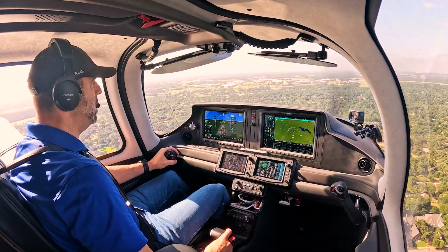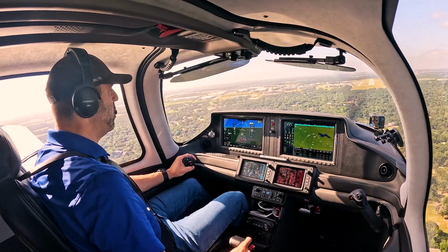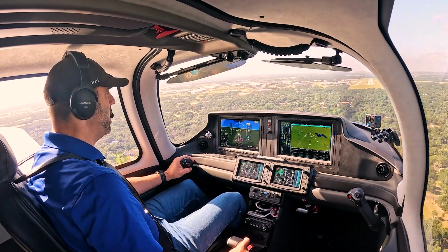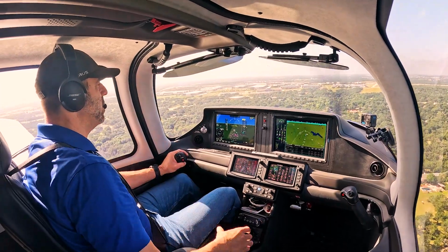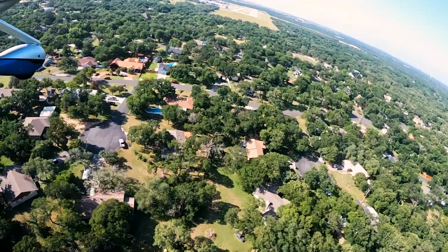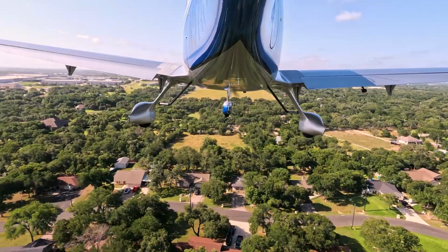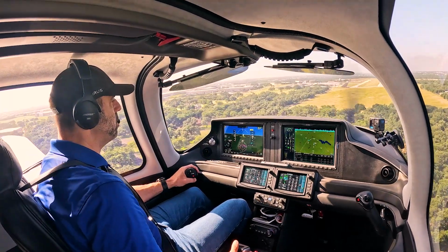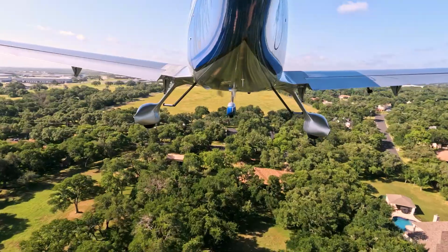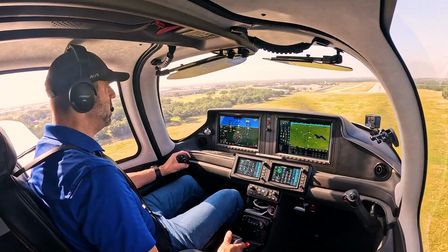So there's 90 knots. So now I can test it, right? What do I need to track on that center line when I get close to the runway? A little left rudder, and now that puts my nose right on the center line. So that's my corrective input. Looking good. We'll start to feel a little bit of that gust over these trees, so you gotta be ready for it. There it is. Little power, 85 knots, slowing to 80, looking good.